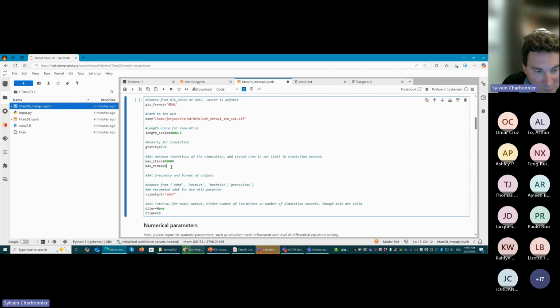And by the way, using the conservation equations of mass and momentum that I was talking about, your flow is never completely going to stop. You're always going to have very small velocities of less than 1 meter per second. But the way the partial differential equations are written, your velocity cannot be 0. So you're going to get very slow velocity for a while, and that's where you're going to be able to say, okay, now I know that the flow is actually not moving anymore.